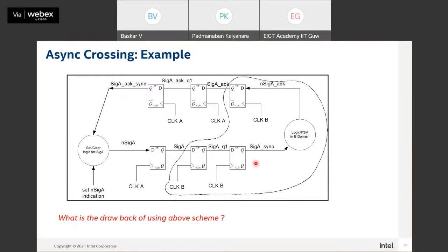So this is the handshake mechanism. It is like I am telling the receiver, hey, I am going to give you new information, you be ready. Then I place the new information on the bus. I will not change this content until I get an acknowledge back from the receiver saying that it has sampled it correctly. The flow is like this: I place data on the bus, send a notification, then B sees it, samples it, and sends me a notification back. I consume that notification, and only then am I allowed to change the data, which means placing new data.